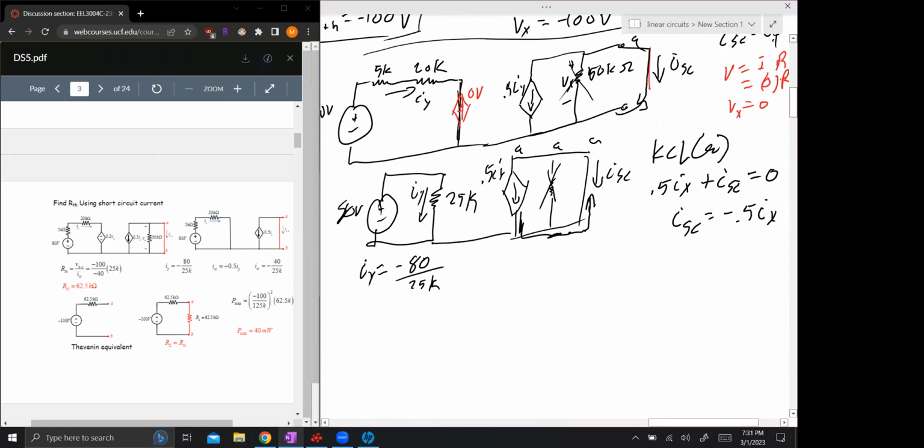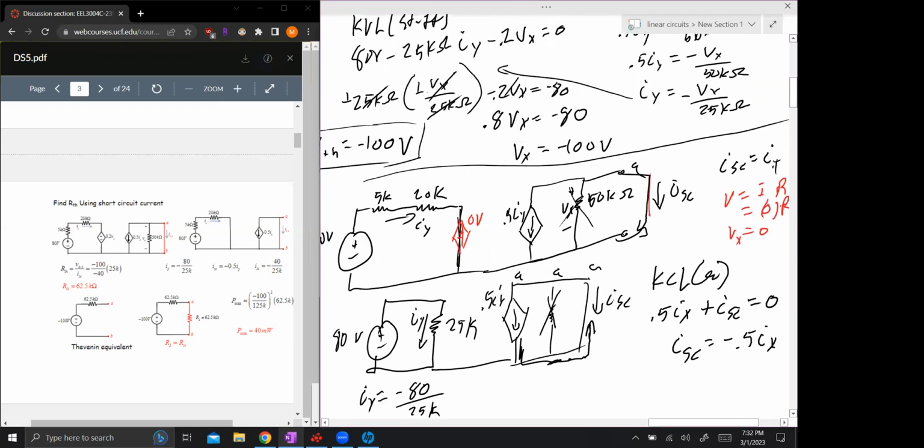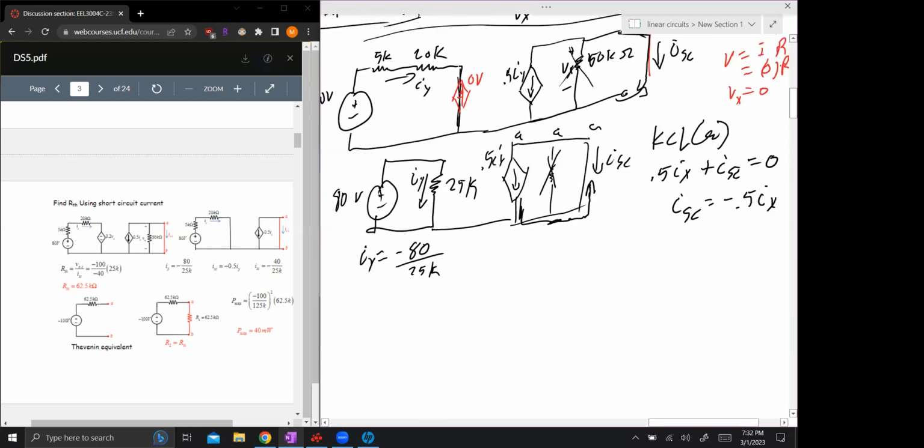What minus sign? Why is it negative then? Because our Thevenin voltage is going to be negative. But we're not using that in this one. When we get the resistance, we have to divide them. Resistance has to be positive, so both of our Thevenin values have to be negative. When we divide them, we get a positive resistance. Remember we got the negative 100.